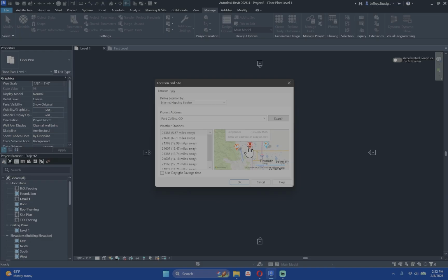You will want to get quite exact with it because on the lower end level of locating this, you will always want to generally locate every project you have at least to the city that you have, because then when you are doing photometric studies and solar studies and inputting the information or linking this into Forma, Forma likes to see these things, and the other location, the photometrics and everything, like to see these items at the correct locations, because then you will see the sun and other weather environmental effects actually replicate what is going on in that area.